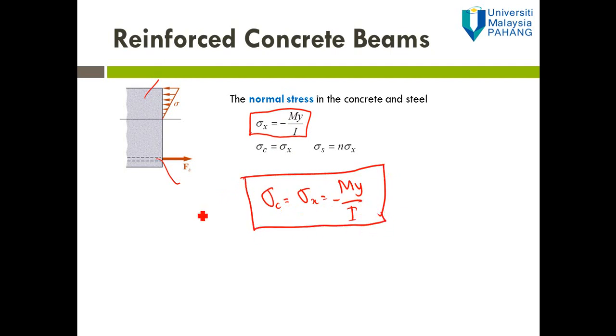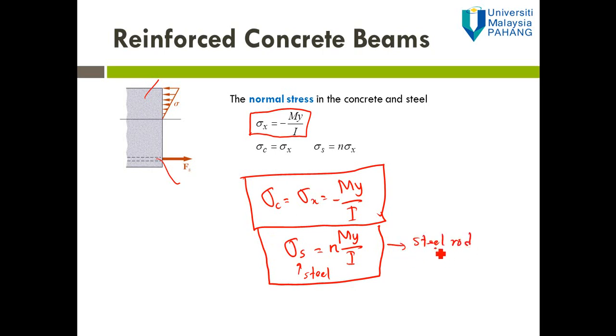For the stress in steel, we apply the same equation, My over I, but we have to multiply by n, because remember, in the previous slide, we transformed the steel rod into concrete.